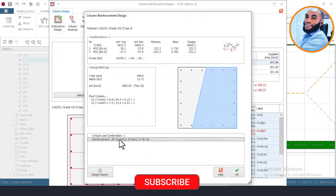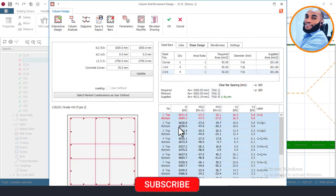You can see that 20 number of Y16. But I would advise for this 16, this is a 16 story building, and I would like to use Y16 for my column because of the high-rise building and all that. So I would advise don't go and increase your column section very much just because you want to have a lesser bar. At least use something that is adequate.